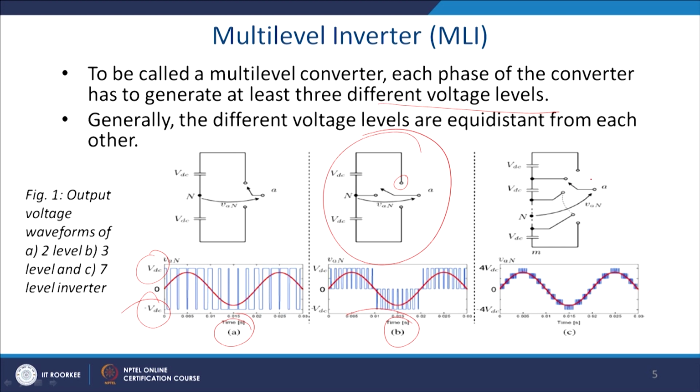So, generally we say this is the multi-level inverter or the 3 level inverter. You can have different levels and you can split this voltage like this, and ultimately you generate this waveform. You can see that it has a very low dv/dt and the number of switches required will be more, but it is very close to the sine wave and the requirement of the filter will be reduced, low dv/dt, all those advantages will be there. And since these switches have to block only VDC by N of the total voltage, the voltage rating of these devices is also going to be reduced.